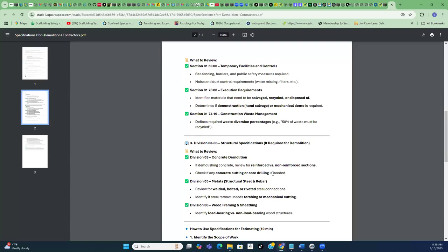But other than that, what do you need to do but knock down the building? When we're keeping the building up and its interior, we've got to demo everything from concrete to electrical. You have to go not only to your existing conditions division, but also to each of the divisions for each of the trades that you're demoing, because each of those, just like concrete, has a demolition portion.